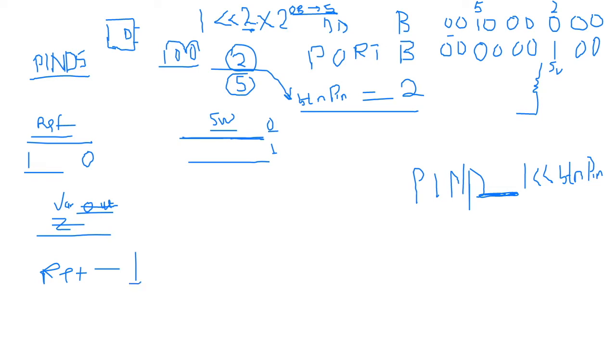So in order to set bit 2 of that reference signal to 1, that's in order to have 1 0 0, what we have done is actually use this line, which is move, or bitwise shift, 1 to bit position 2. That is all we've done at this point. So this is our reference signal, so we know definitely that we are setting bit 2 to a 1.